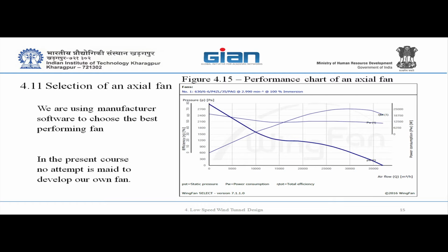And then they measured the velocity distribution on the surface, and they accumulated it to get the flow rate, and it is exactly what they meant. The only mistake my dear students made is they were calculating the speed in the test section according to the zero point, not to the working point.